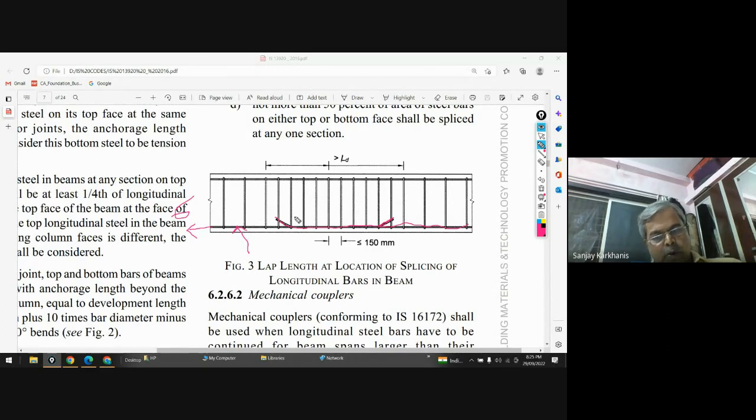और दूसरा बार, तो ये जो दूसरा बार है, see the stress from this bar is transferred on the concrete, and concrete will transfer the stress on this bar, and that transfer mechanism must be smooth. If it is haphazard, then there will be cracking, and you will always find wherever there are insufficient development length provided at the time of lapping, you find some sort of cracks in the beam, and that crack is getting developed and it is further improved like this.